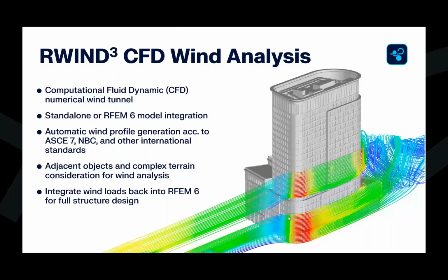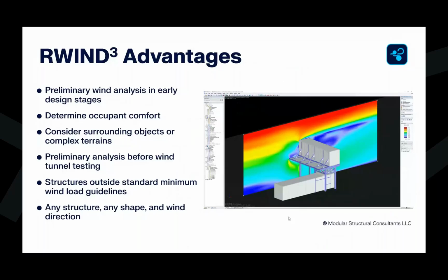But ultimately, when we close out of our wind and back into RFEM 6, these loads, the wind pressures, are automatically taken and converted to static wind loads on every FE mesh element. That way we can then combine with the other load cases like live load, snow load, and continue on with our analysis and design.